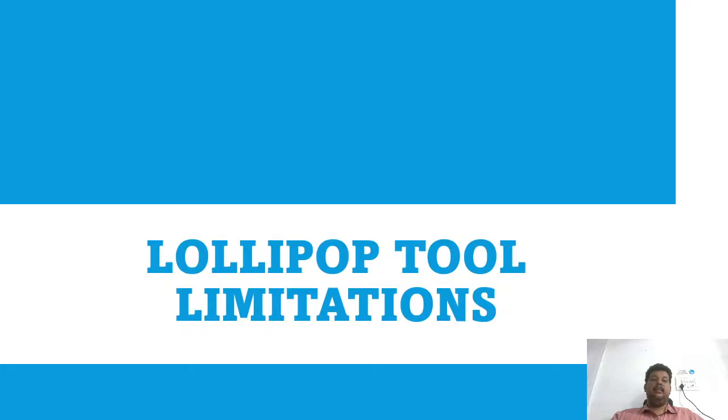And finally, the programming must be very, very careful. Right? The toolpath, the step over, the step down, everything should be controlled. Because one small mistake can lead to collision or tool failure. So always remember, this is a precision tool, not a power tool.